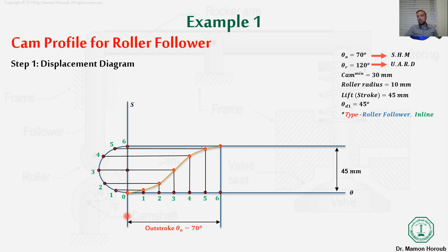It will give you S directly, and you can draw the curve directly based on the equation. So you have two options: use the equation and plug in different thetas to get your S, or follow the procedure that I discussed before, where the half circle is divided into 6 pieces and your period is divided into 6 pieces. Just make cross lines between those points. It will give you the dots that draw the simple harmonic motion for you.